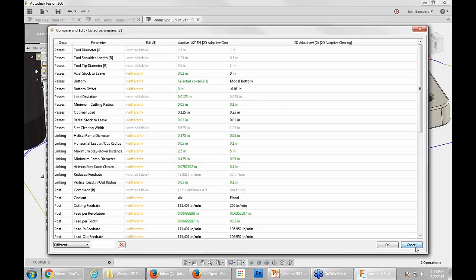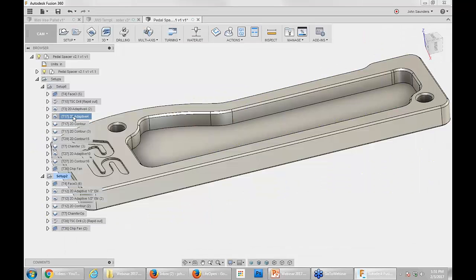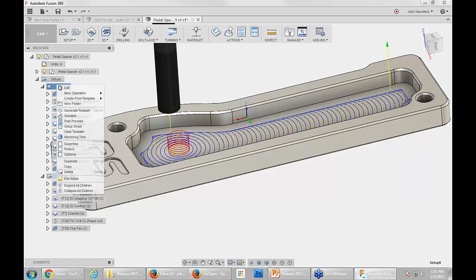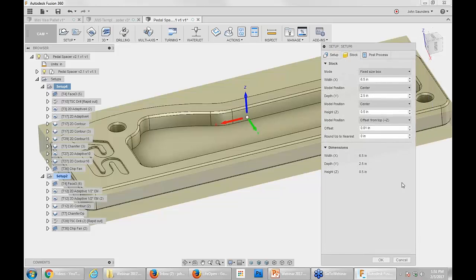Right. I am seeing a question in regards to having multiple work offsets, and does it work in Inventor HSM? Yes, that works in all three of the products. If you're doing multiple of the same part, want new work offsets, and it's in the setup, multiple work offsets. If it's multiple different setups, I use that post option, but yes, that's in all three products.